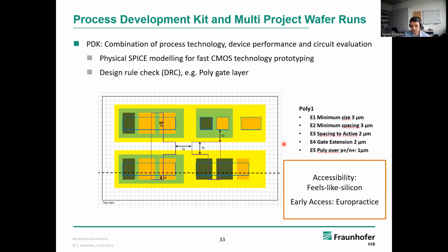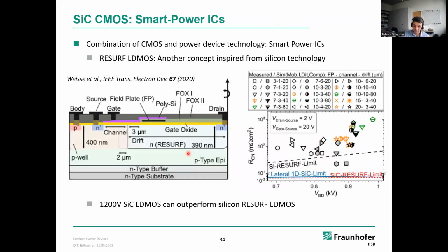Of course, you have to modify the chip areas, P and N areas, and maybe temperature compensation will work a little bit differently here. But overall, multi-project wafer and all these concepts, of course, will work the same. And then ultimately, and this is also something that we're developing at ISB at the moment, high temperature transistors, LDMOS transistors for an integrated half bridge, for instance.